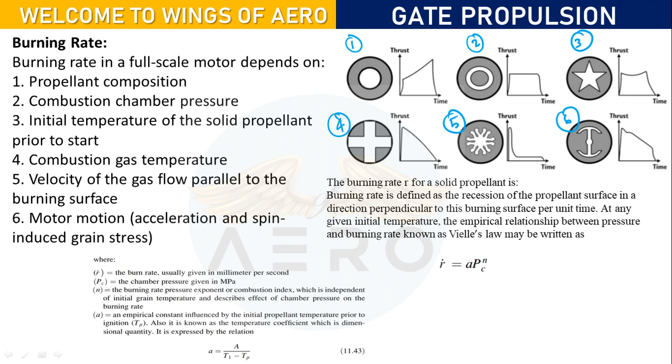It will be the second one, where you can see it is very flat, which means it defines neutral burning, right? The 1 and 3 you can see are also kind of progressive, it gets ups and downs, and 4, 5, 6 you can see are regressive, right?